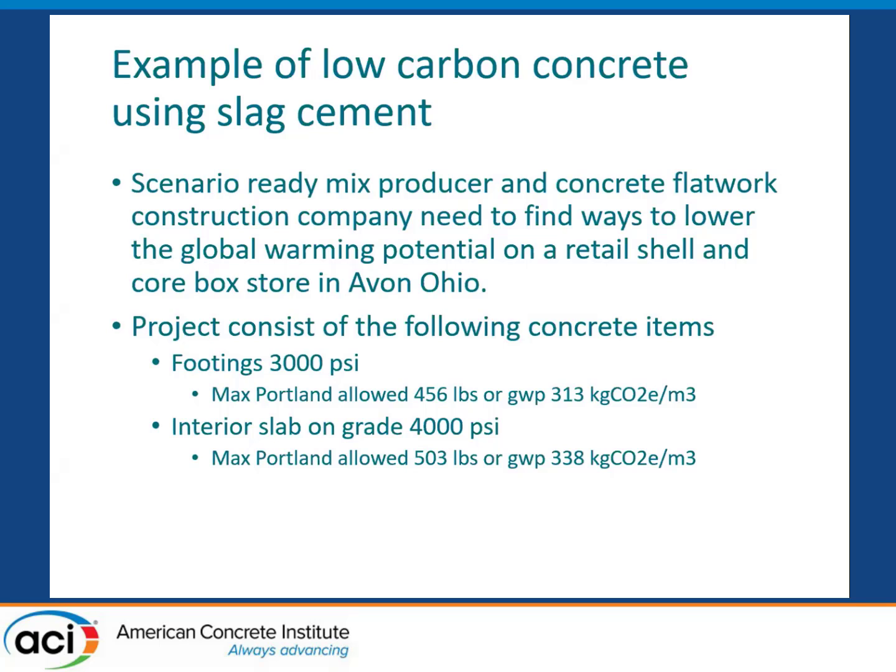Here's an example now of low carbon concrete using slag cement. In this scenario, we're going to use a ready-mix producer, a concrete flatwork construction company, and they need to find ways to lower their global warming potential on a residential or a retail shell and core box store that's going to be built. And this is fictitiously put in Avon, Ohio. So in this case, the project consists of the following concrete items. There's a 3,000 PSI for the concrete footing, and then there's a 4,000 PSI for the interior slab on grade.